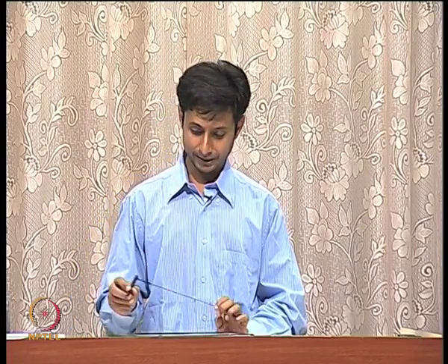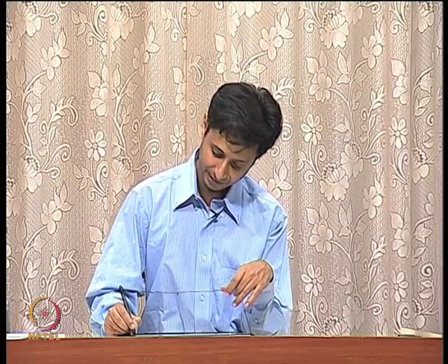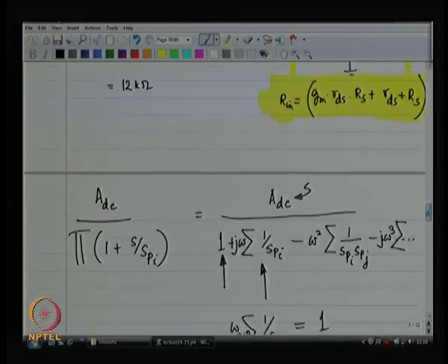I did not want to see 1 kilo ohm, I wanted to see something much lower resistance. If you would drive this huge capacitor with a low impedance, then you would get a much smaller open circuit time constant for that particular one.